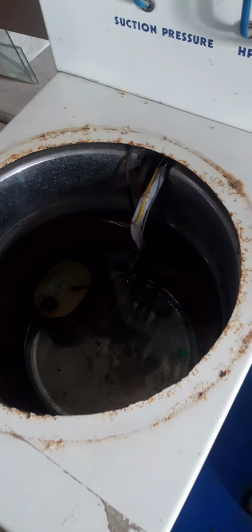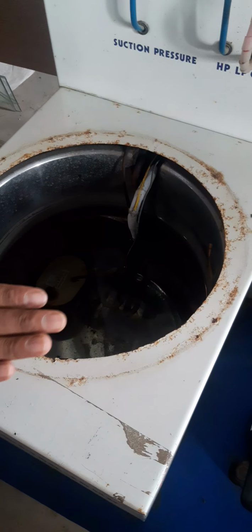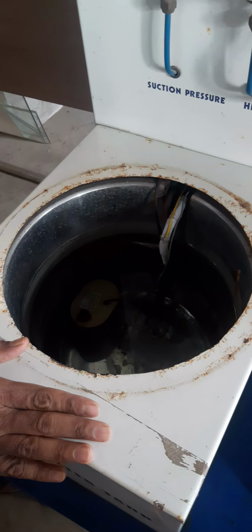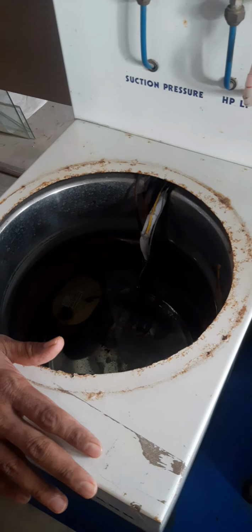How much water is getting cooled, or what temperature is maintained after the cooling, is the refrigerating effect produced, and how much work or energy is consumed by the compressor to make it cool. That we are going to calculate, and that is how we find the COP of the system. In this setup a pump is there to stir the water, and a heater is provided to maintain the temperature of the water. Whenever we cool the water, simultaneously we heat it and measure the temperature of the water, so that the energy consumed by the heater can also be calculated.